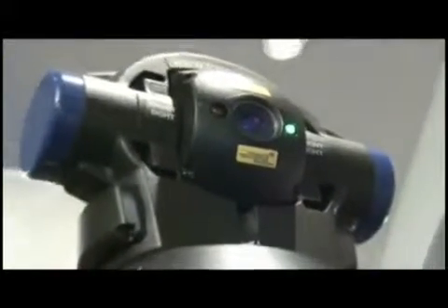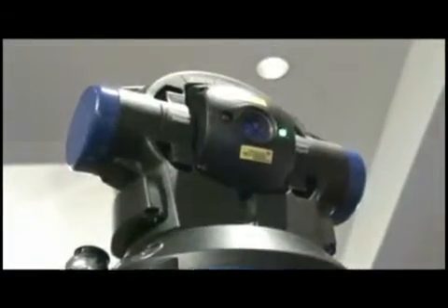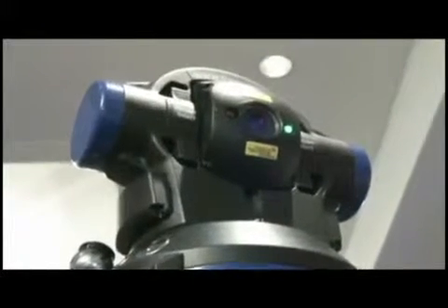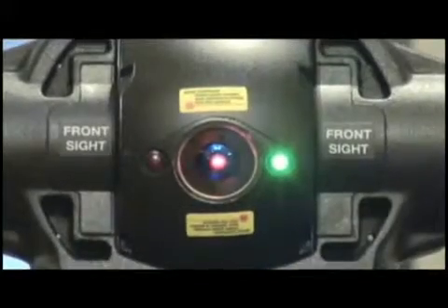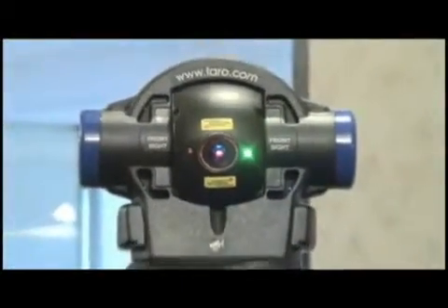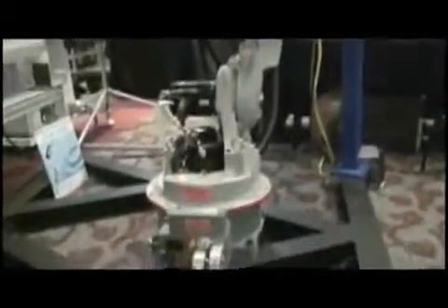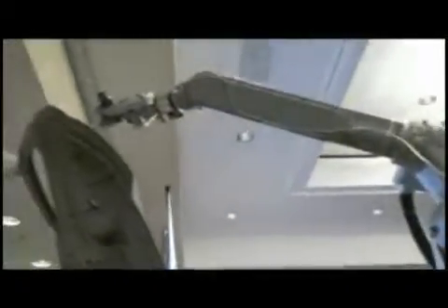During identification, we are measuring the robot, in this case with the laser tracker, and then we use that data to calculate all the parameters of the robot arm. There are quite a few parameters that make up the geometry of the robot, as you can imagine, and all of those stack up one on top of the other to give you the accuracy at the end of the arm. At the end of the identification process, we will have a parameter file, which is basically a signature of the geometry and the kinematics of the robot. And we'll also have an alignment file that gives you the relationship between the base of the robot and the fixture. With those two files, then we move on to the compensation phase.